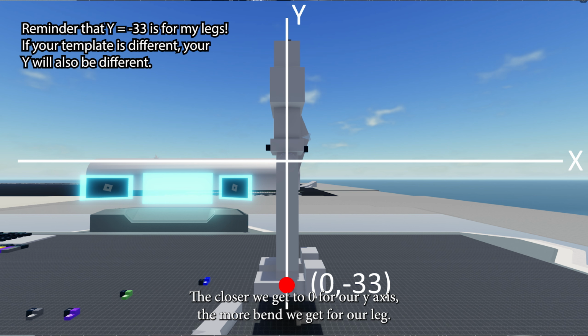We'll rename leg resting height to leg height, leg moving height to leg stepping height, and we're going to add an extra constant and rename that to leg stepping length. Do the same thing for the arms as well. Delete the multiplication block under the animation speed, and now let's duplicate the configuration that we just edited.